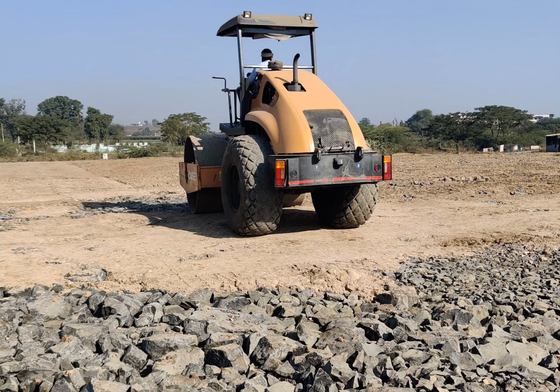So this is the typical photograph of the rockfill embankment construction, which indicates that you have the rocks being filled, and on top of the rock you have the fine materials being laid to fill the gaps or seal the top of the rockfill embankment, so that it will help the rollers and the other equipment to move smoothly.